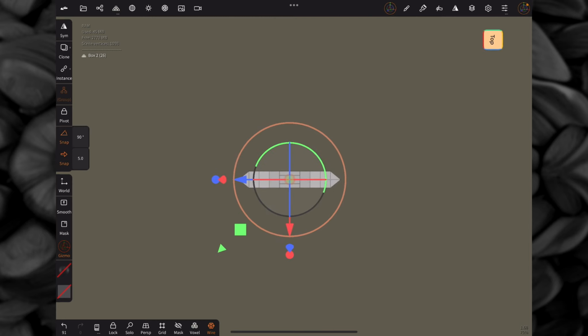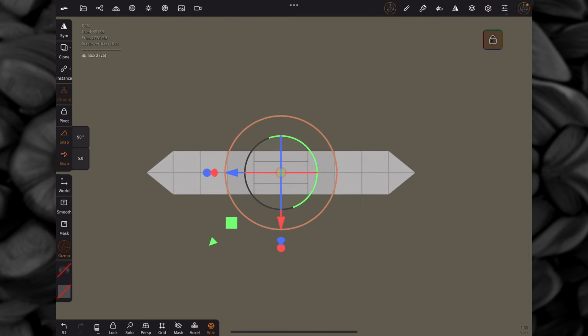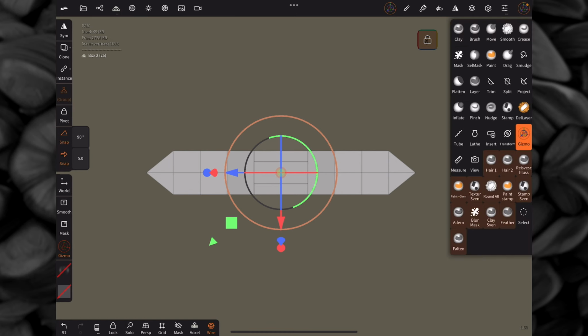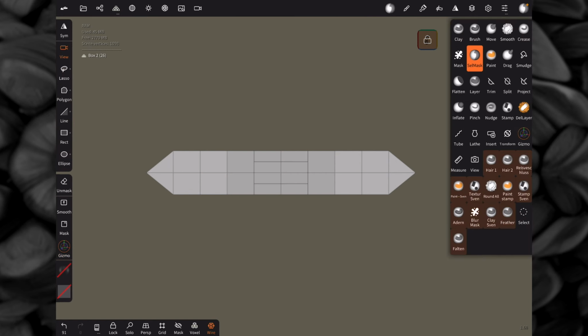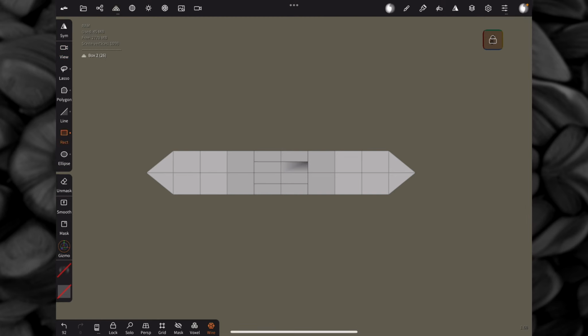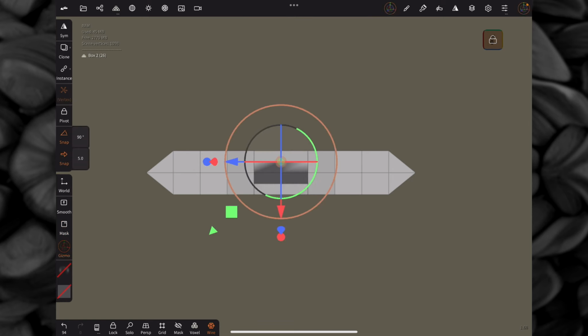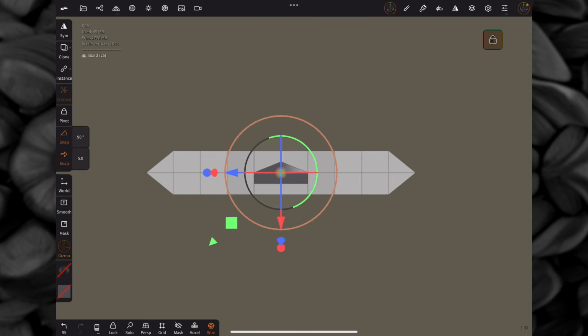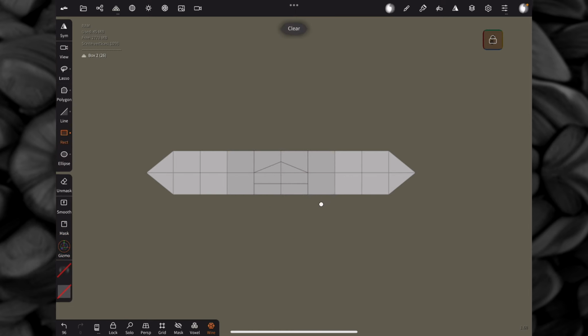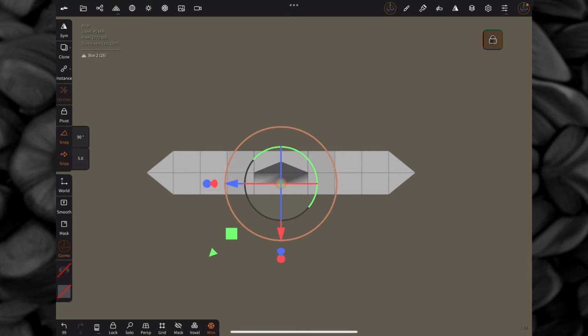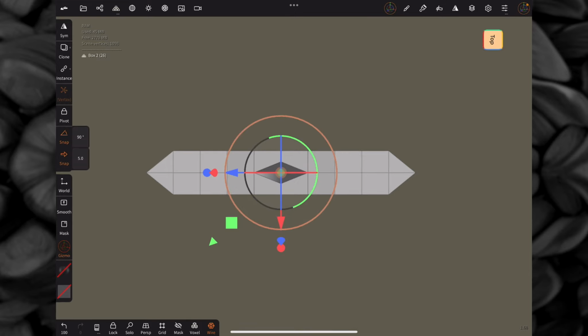validate it, lock the top view, and use the same techniques as before with the selection, rectangle, select the corners, flip your mask, move the gizmo one snap down, clear your mask, select the lower corners, flip your mask, gizmo one step up.